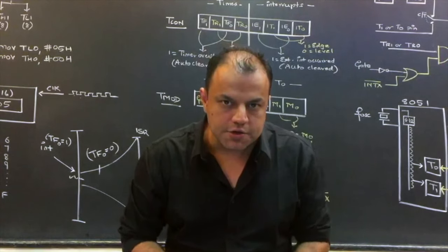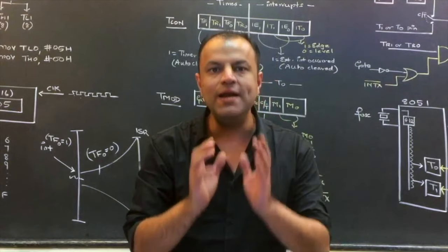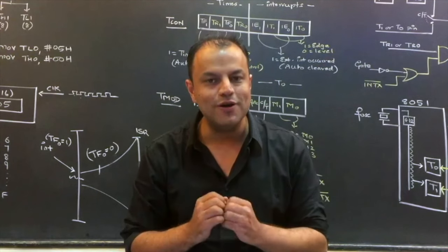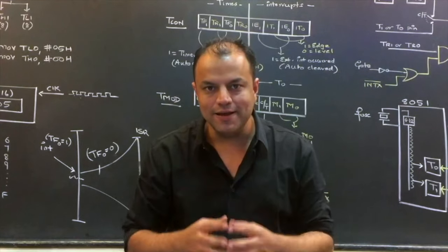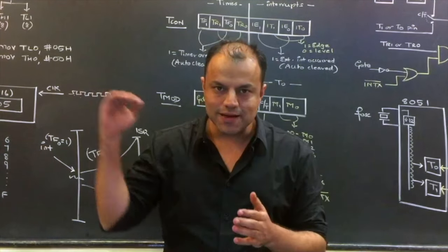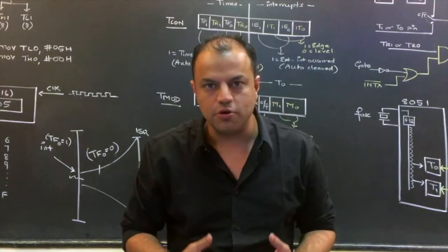So somebody should have reminded the processor that I am pending. Say again, I am what? Pending. This is a technical word. A pending interrupt is an interrupt that has occurred but not yet been serviced. So pending interrupt should not be lost.